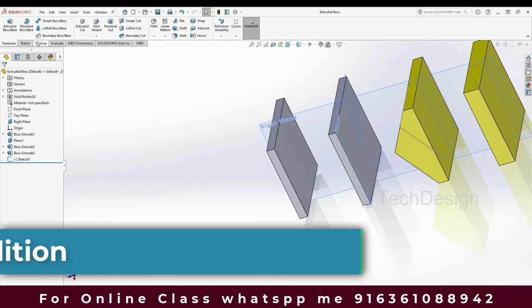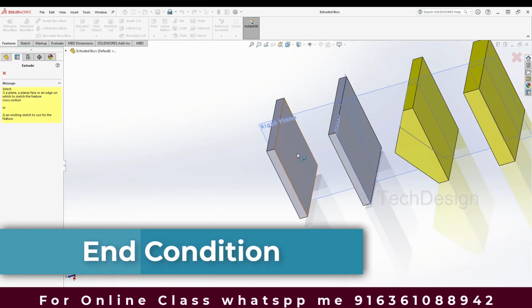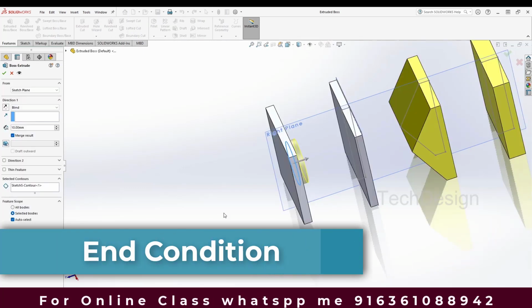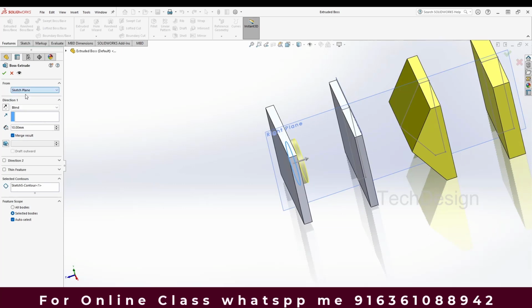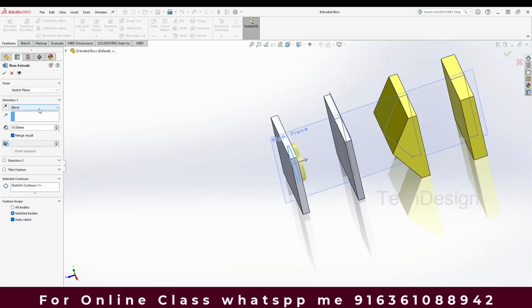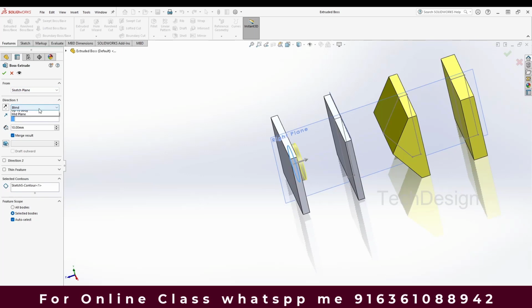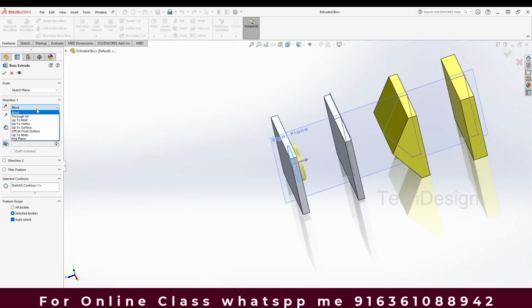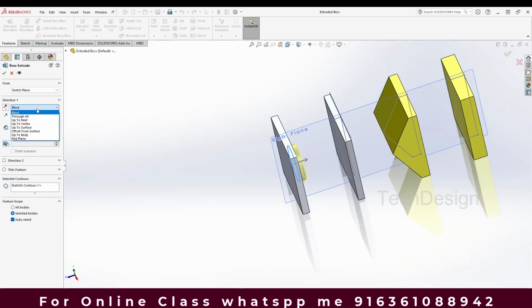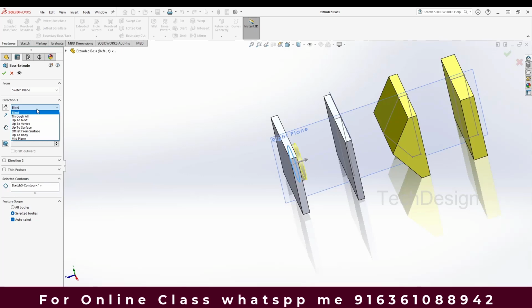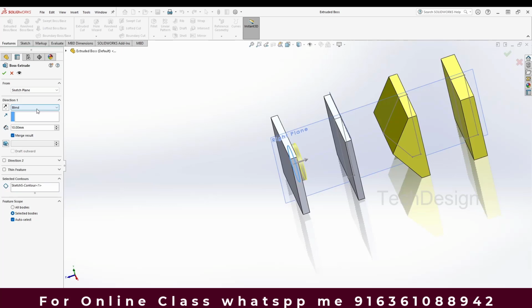The next will be the end condition. How are we going to define the end condition? There will be 7 types of end conditions. I'm going to keep the start condition as a sketch plane. So what are those 7 types? Blind, Through All, Up to Next, Up to Vertex, Up to Surface, Offset from Surface, Up to Body, and Midplane. These are the 7 types that are available in the end condition.